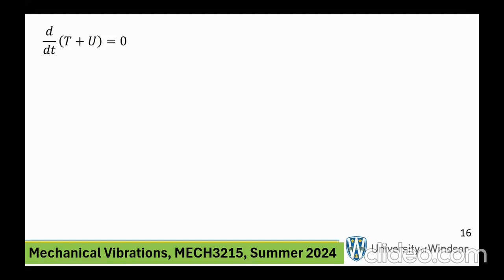Notice that there is friction here, but that friction happens to be taking place at the contact point, and the contact point on the ground is not moving. So that friction does no work. There is friction here, but there is no loss because that friction force does not do any work. So be careful, because otherwise you might say if there's friction, there must be losses. Well, you have to be careful.